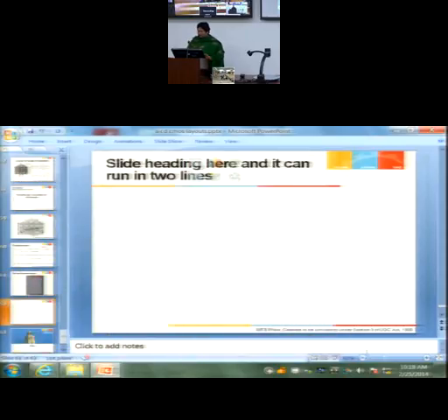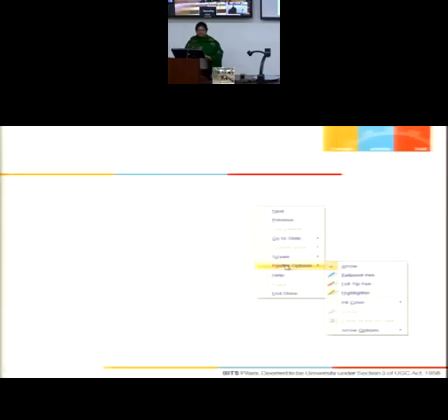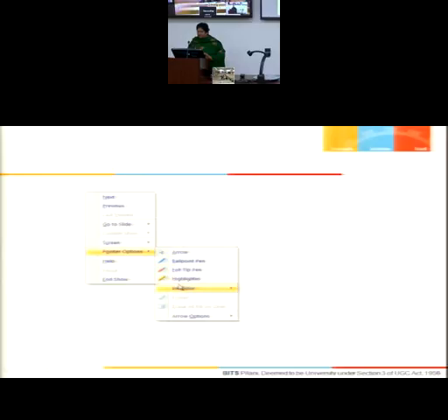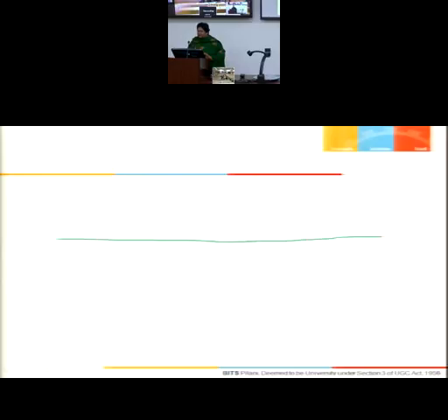Okay. Let me show you how to start doing a bigger transistor of 80 lambda by 4 lambda. I actually split it into 4 transistors, each of width 20 lambda by 2 lambda. Okay. So what I do is I take a width. Let me change the color so that you can see. So let me take an active which is green in color. So I have an active region. This width is going to be how much? 20 lambda. Lambda I am not writing, that is understood. I am going to have 20 lambda.